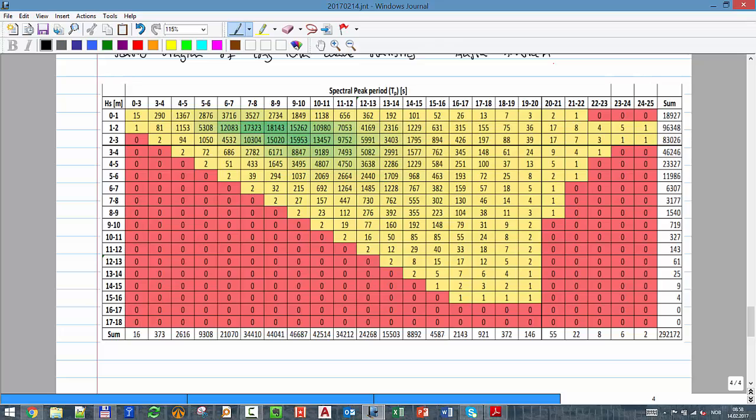So what you see here, at the top, TS, or they call it spectral peak period, that's where you have the peak, and HS, on the vertical axis, tells you the significant wave height. So you have a collection. First you have a range. What we really measured was one state, for example. If you get one TS and one height, you put it here. So that's one state.